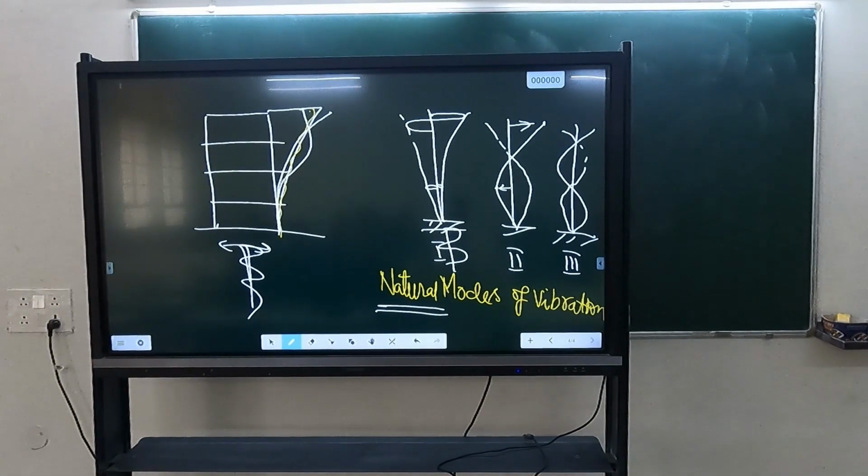The second observation was that the damage was selective. It occurred only between 5 to 20 stories. Why? Because of the filtering action of the ground motion. When the ground motion was transmitted through the soil, all the energy got focused around the fundamental frequency of that soil column. So if you see the shape of the response spectrum, we get a peak around 2 seconds.